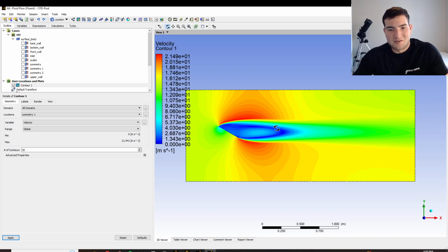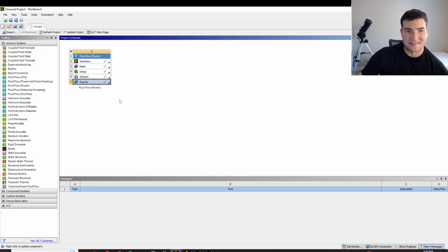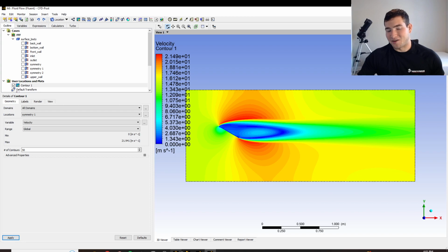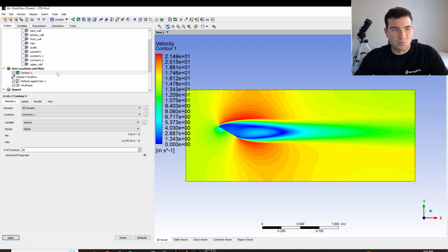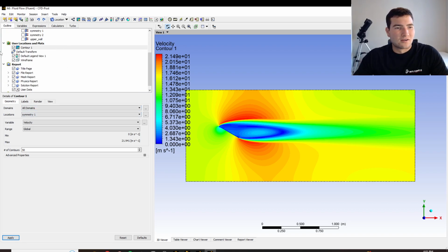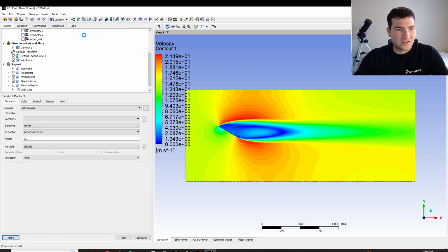I've had it give me like a weird hurricane behind the plate for some reason, and there was no velocity even coming out of the inlet. Not sure what was with that, but like I said, that was in the workbench with the others, and I opened a new workbench like I did here, and that fixed it. So maybe there's something weird with the cache. I'm not sure, but I've been having a lot of problems with this project and just weird stuff like that happening.